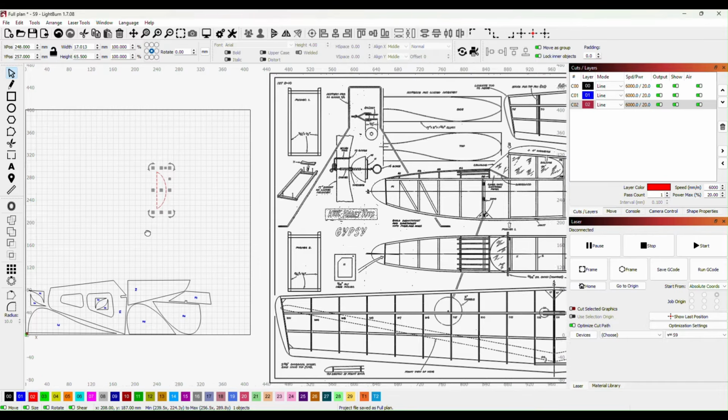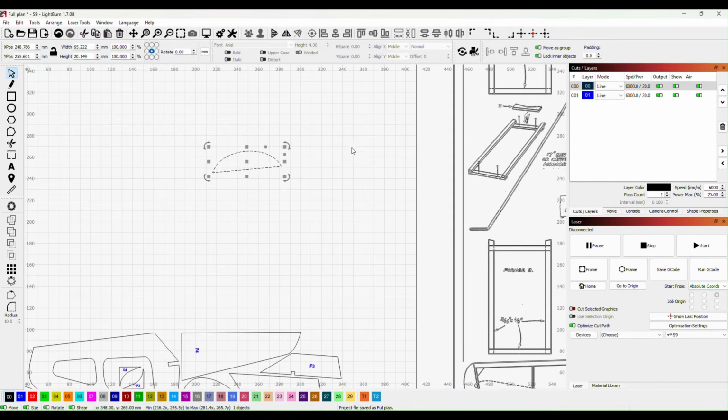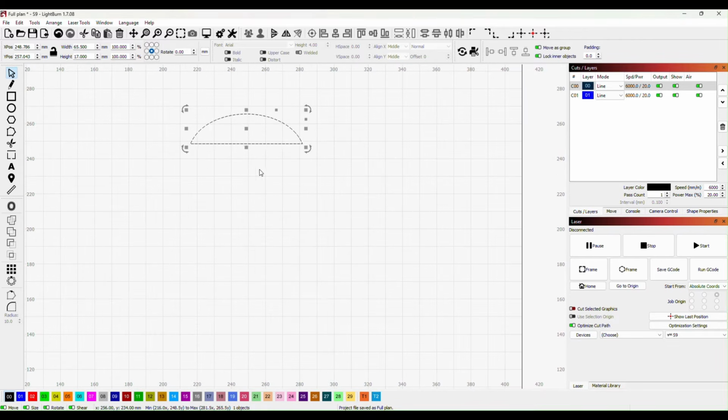Now if I bring it over, there is another thing we can do as well. I'll just change that back to the cutting layer. Now remember how we get this level. We go on nodes, we hover over one of the sides while we're in nodes, and we press A, and we now know that that is absolutely flat and level. So if we come back off there, the one last check we can do is press Control C, then Control V, so we've got a copy.